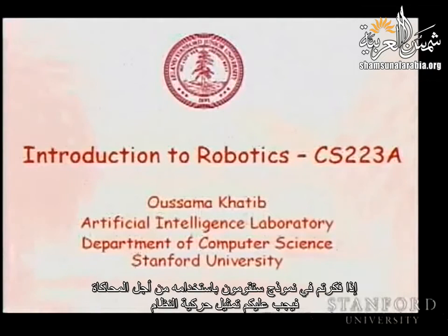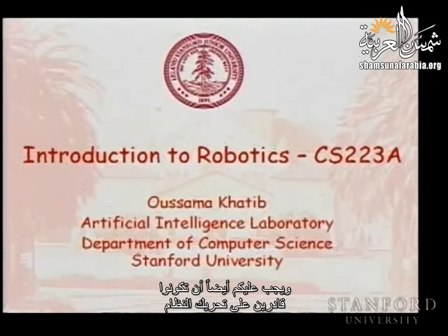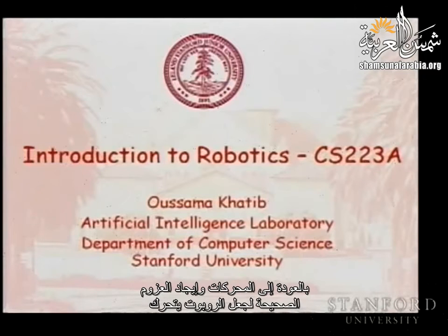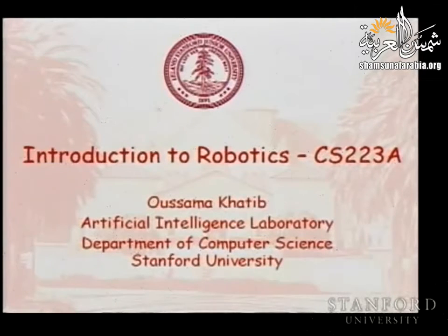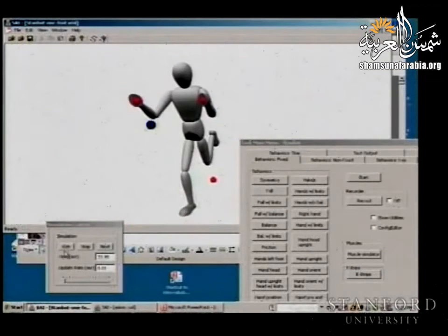And if you think about a model that you are going to use for the simulation, you need really to represent the kinematics of the system. You need also to be able to actuate the system by going to the motors and finding the right torques to make the robot move. So let's go back to this. I think it is quite interesting.